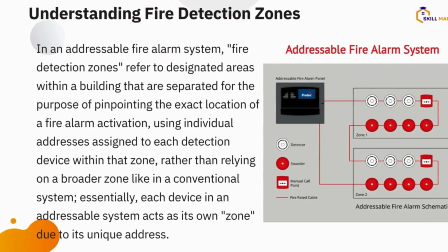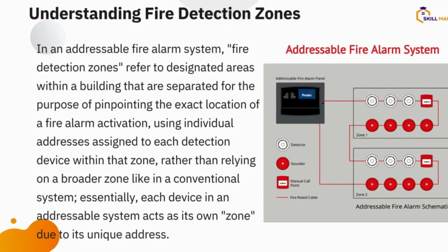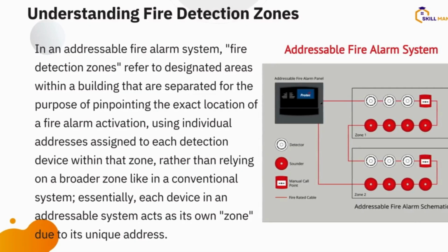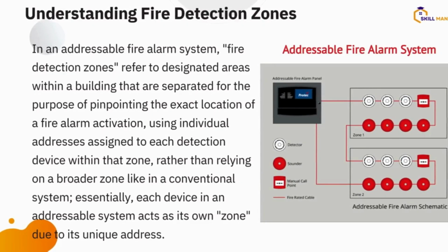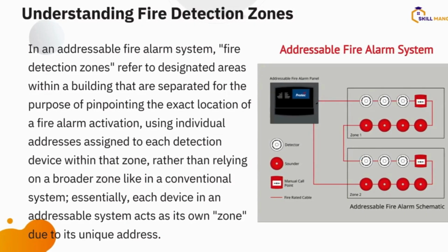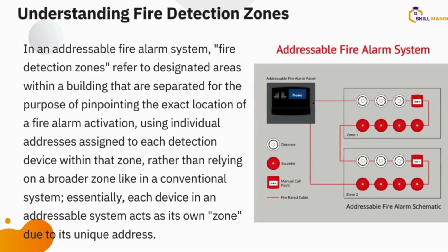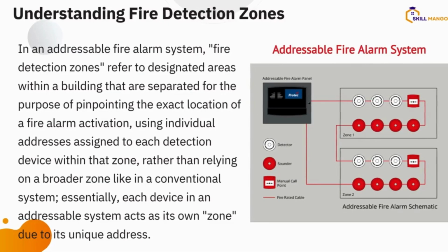Living room upstairs, living room downstairs, lobby, kitchen ground floor, kitchen first floor, call point first floor, call point second floor. So when there's a fire outbreak, you know the actual point where the fire is coming from, the actual location. So you can go there and address it and quench the fire. So it's very important, and this is ideal for skyscrapers, for high-rise buildings, condos, because it's smart. You can address a fire at the point where it is going on. You'll be able to identify the actual point where the fire is coming out from and go and address it from there.